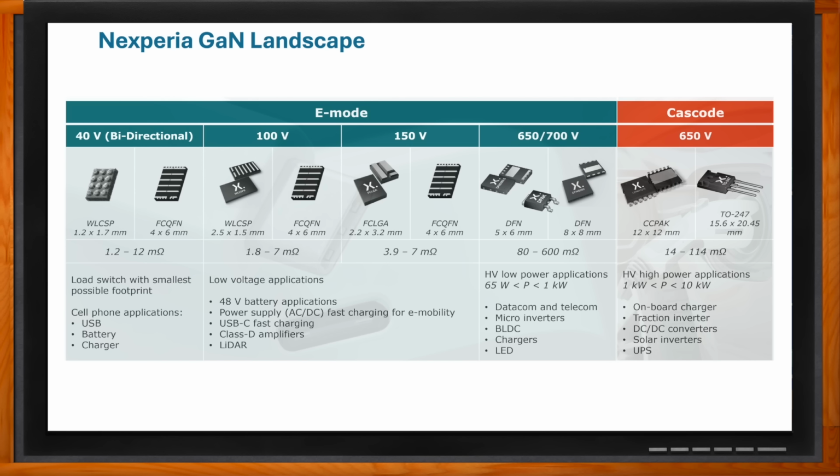And so the higher the bus, the easier it is to drive, and you can still drive it at the higher frequency. That's a pretty good idea of where the GaN is proliferating. And you can drive our 650-volt GaN and soon 700-volt GaN at up to 1 kilowatt. And so datacom, telecom, microinverters, DC motors, chargers, LED drivers, and the GaN is really proliferating itself into just about every industry in cases like that. It makes it easier to work and easier to understand where we are.